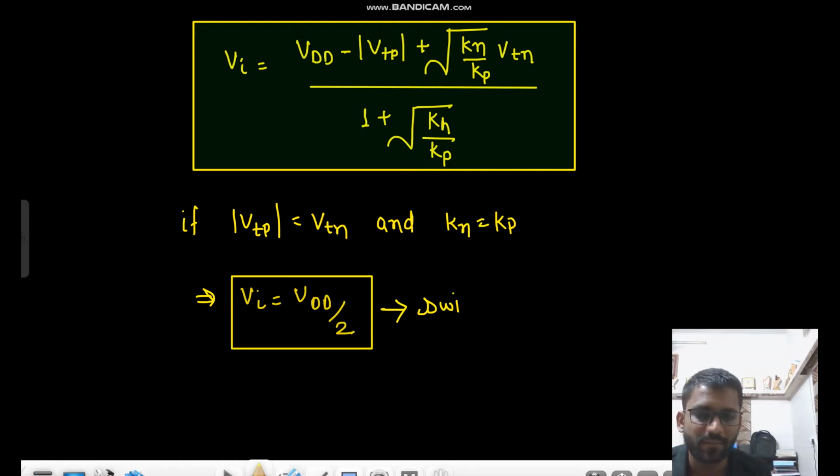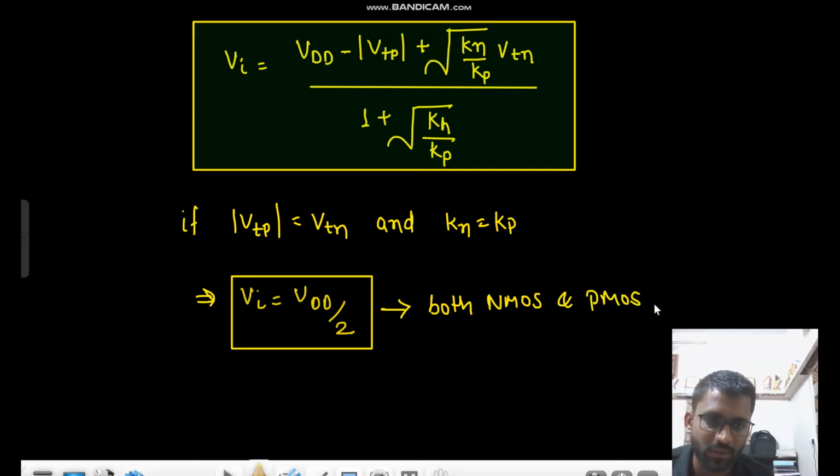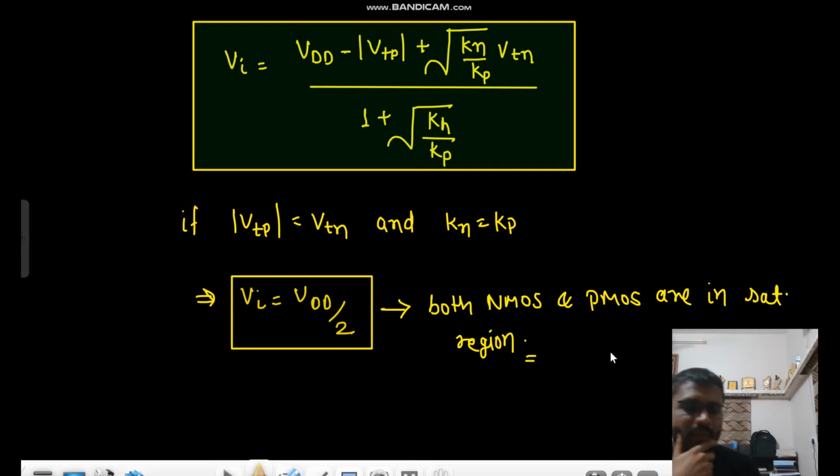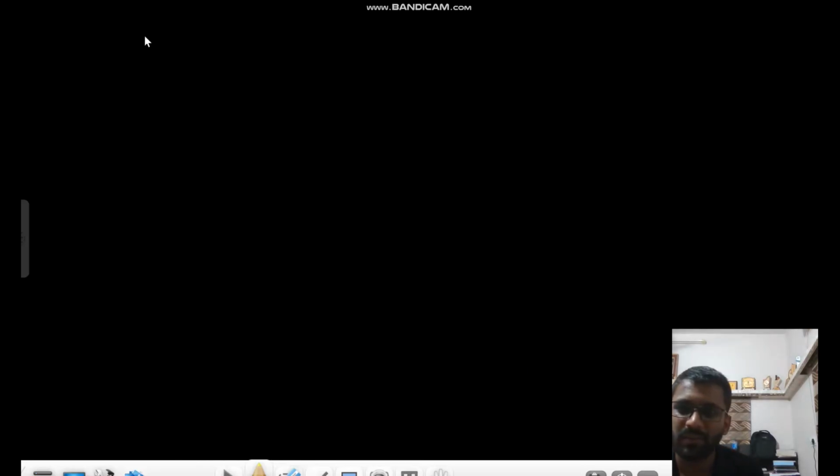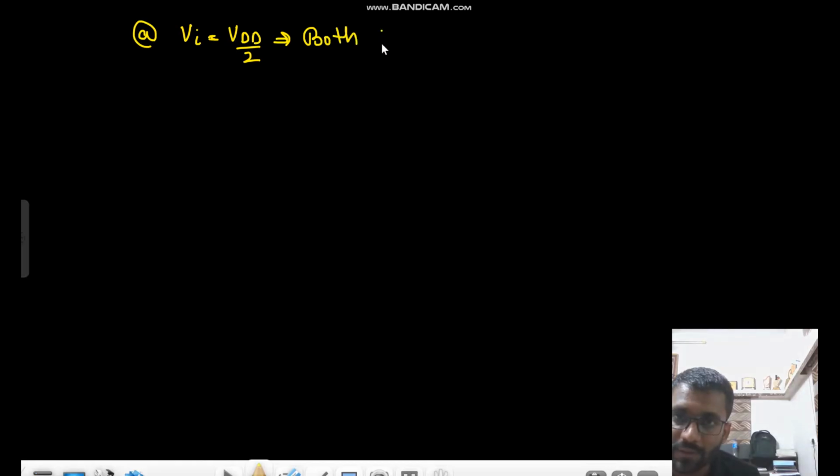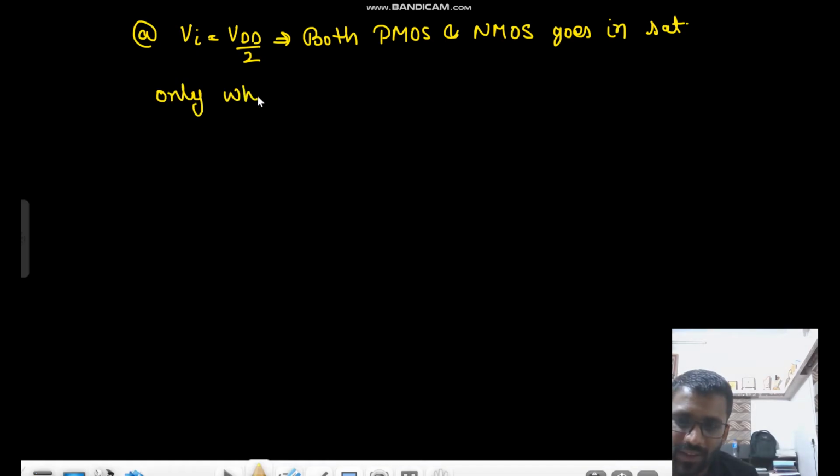What is switching threshold? At this point, both NMOS and PMOS are in saturation region. Okay. So what we have seen is that there is one necessary condition: Kn equals Kp. At Vin equals VDD by 2, both PMOS and NMOS go in saturation only when Kp is equal to Kn, right?